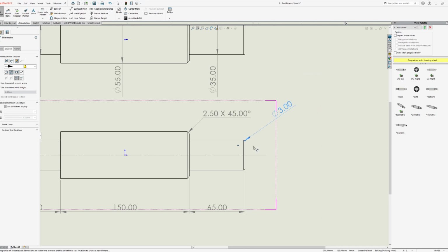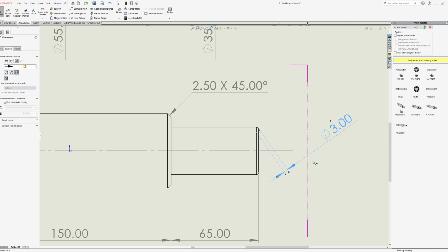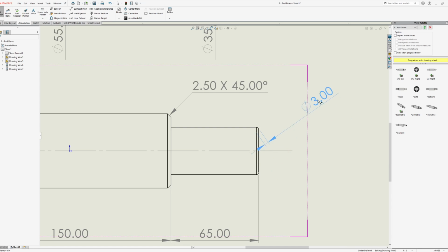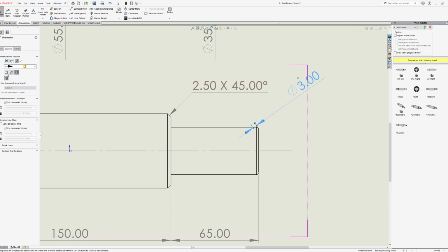Now, for something like a fillet, this isn't optimal. We typically want to have radius values for arcs and fillets. So I would try to stick with using your radius option that's here. But there are different ways that you can show it. Perhaps I wanted a linear one, where it's just showing the two different sides from one end to the other of the diameter of that arc. Did it change? Oh yeah, it changed a little bit, which doesn't really give me too many options.